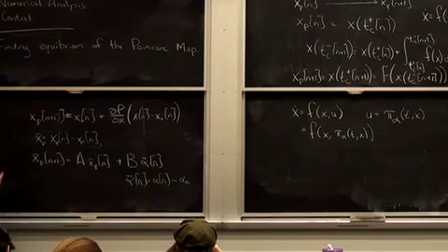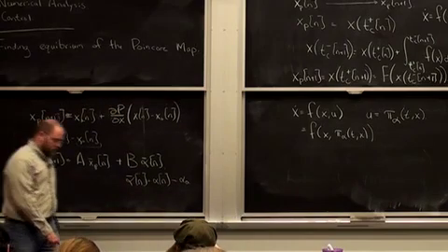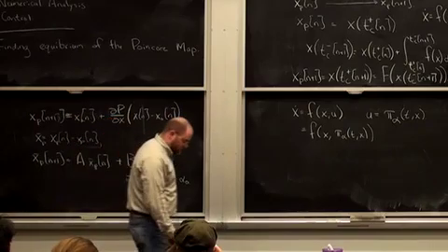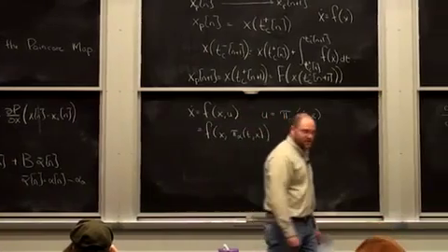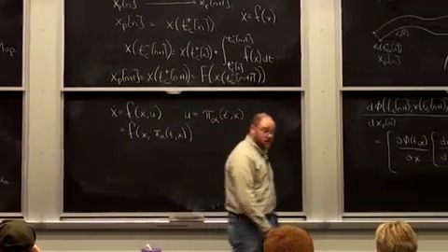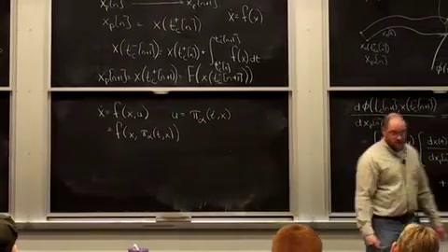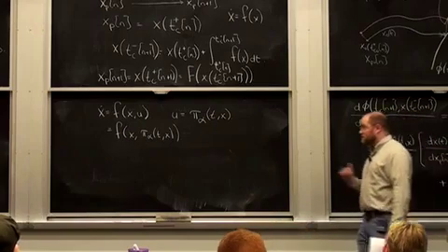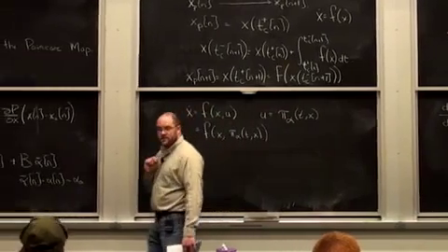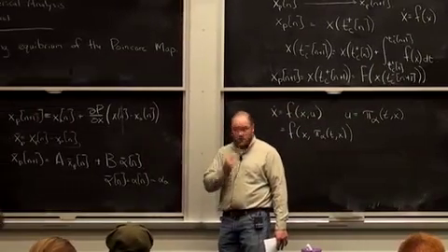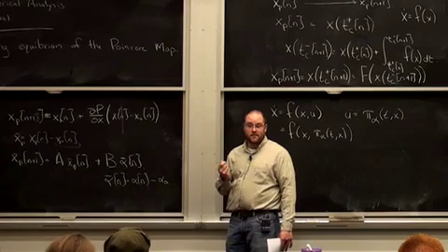Let's say I find a stable limit cycle where I just command the inner leg angle to be, I don't know, pi over 4 every step. And I can find a stable limit cycle behavior. Well, then if someone pushes my robot, computing these A and B matrices gives me a nice, simple way to make discrete decisions to try to stabilize that robot.